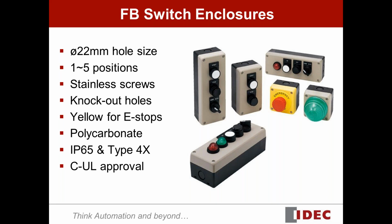And you can see there's one of the boxes, P boxes. You can see the knockout hole on the top, so it's very easy to knock it out and put a gland connector in to do the wiring. We also have a yellow version that's designed for e-stop application. The boxes are made from polycarbonate, but they are IP65 and Type 4S rated. We also have the UL ratings on that.